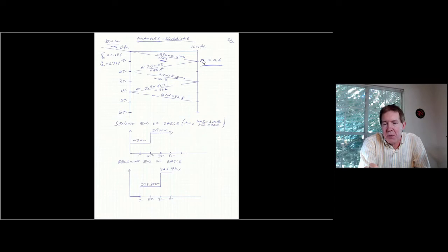It's going down toward the 200 ohm load. Once it hits that 200 ohm load, it reflects back with the reflection coefficient of 0.6. So I have 0.6 times 143 being sent back. Now, what's the voltage we see once that waveform hits the 200 ohm load? Well, I have to take the 143 plus the 85.8. It's a summation of those two, right? So that's what I would have in my diagram.